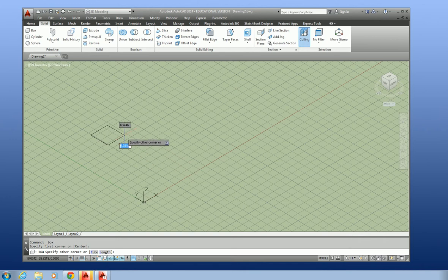Okay, so let's hit the tab, and this will help us go from one box to the other. Let's make this one 10. Let's go this direction to 10, and don't hit enter. It's a common mistake. Don't hit enter, because in AutoCAD you hit enter for everything. But you want to remember to include tab sometimes. So hit tab, and this gives us our next direction. Let's make it a 20. Now hit enter. And then the next thing it wants to know is our height. So let's make it 10. And then there's our basic